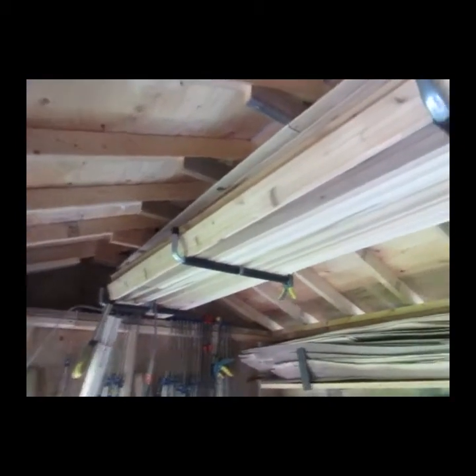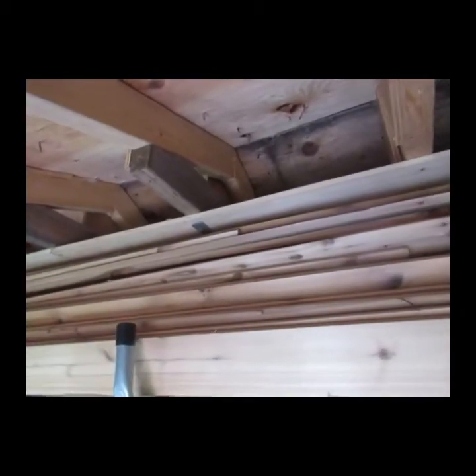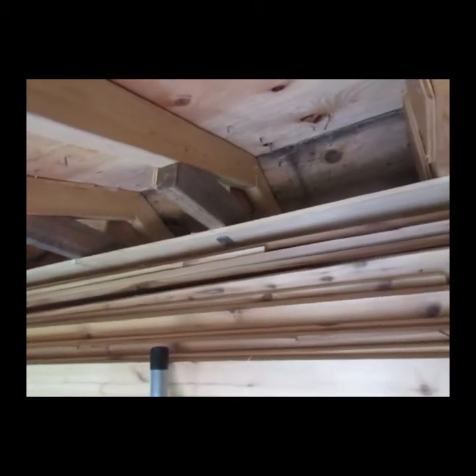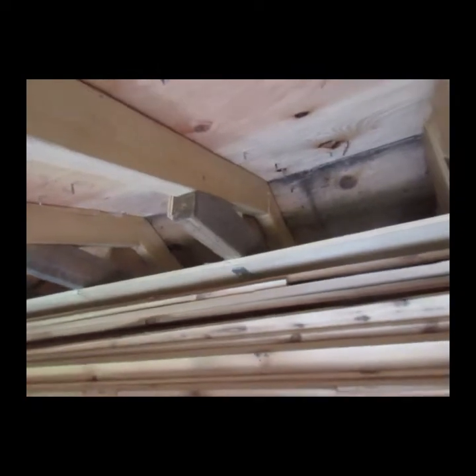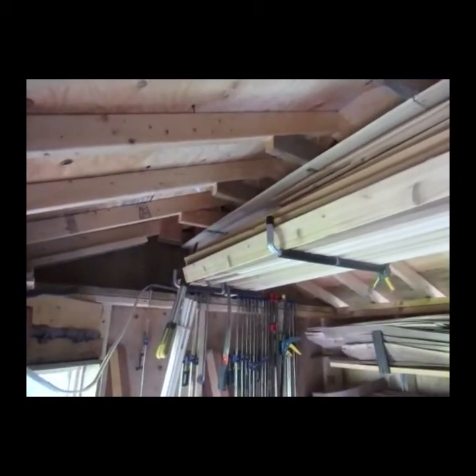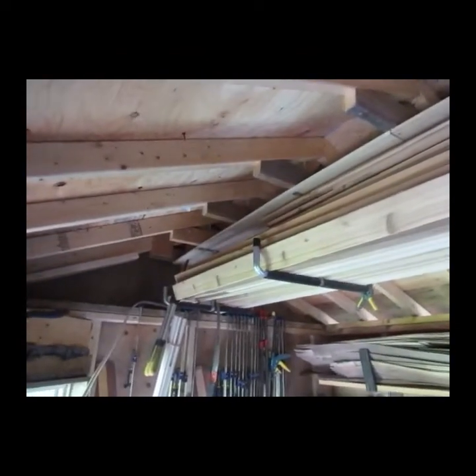Now, if this was a larger structure, those two 2x4s could not meet like that. They would have to tie in to a board called a ridge board. Now, look again to the right, and you'll see a notation that indicates what a ridge board is and how it needs to be put in place and how big it's supposed to be. Technically, the ridge board has to be one size larger of nominal size from the 2x4. So if this is a 2x4, which it is, then that ridge board would have to have been a 2x6.